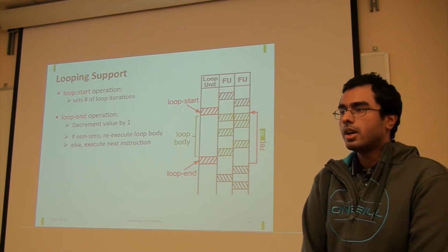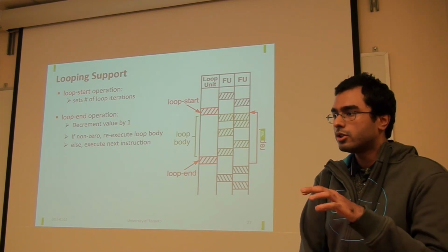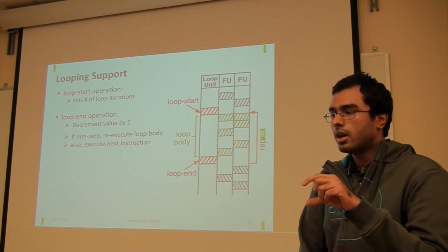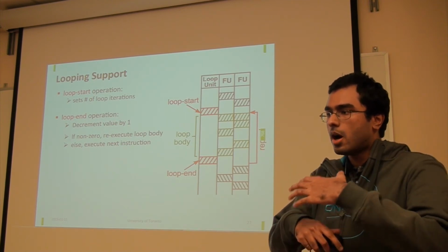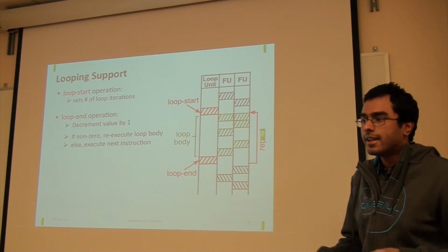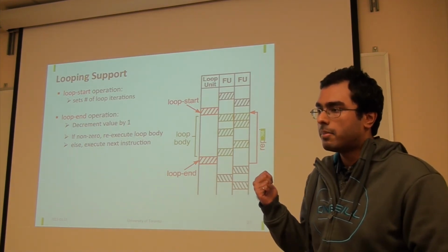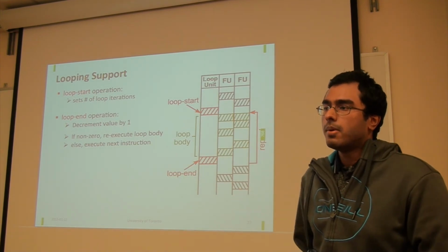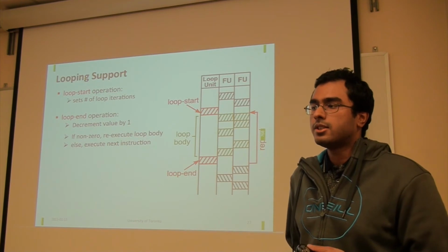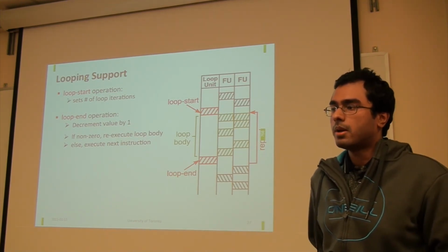For example, in your software code, you can change the unroll factor, how many times that body will be unrolled, and that changes the amount of compute resources that are actually used. And that's how I produced the FIR results. But the main point is that with OpenCL, the compiler can do it. It just doesn't do it as efficiently as the full compute pipeline version.